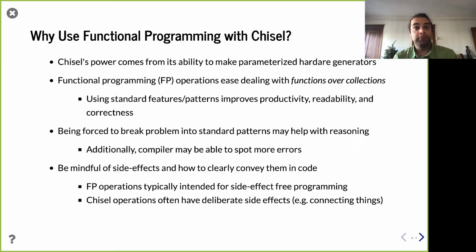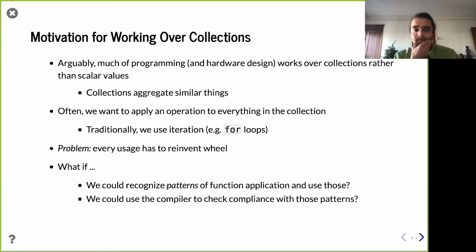One of the things that comes up with functional programming is that normally it's supposed to be side-effect free. Chisel, the way it works, very much has side effects. We're connecting things together, saying, hey, I have this wire, it's connected to this adder, and this adder is connected to this register. So we're deliberately counting on side effects. Sometimes if you operate on Chisel elements with these functional operators, and you forget that these Chisel elements are mutable and internally changing, occasionally there can be a weird situation. So you should be mindful of that. But we'll talk about this when those come up.